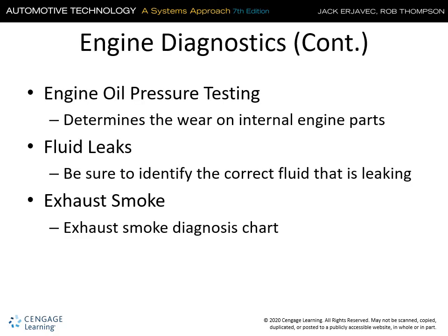Engine oil pressure testing. Essentially, you can unscrew the oil pressure sensor, and it's typically a 1/8 or a 1/4 inch NPT adapter that goes to your oil pressure gauge, and you can determine if the engine does in fact have oil pressure, and whether it's failing from the oil pressure sensor out to the control module and over to the gauge.